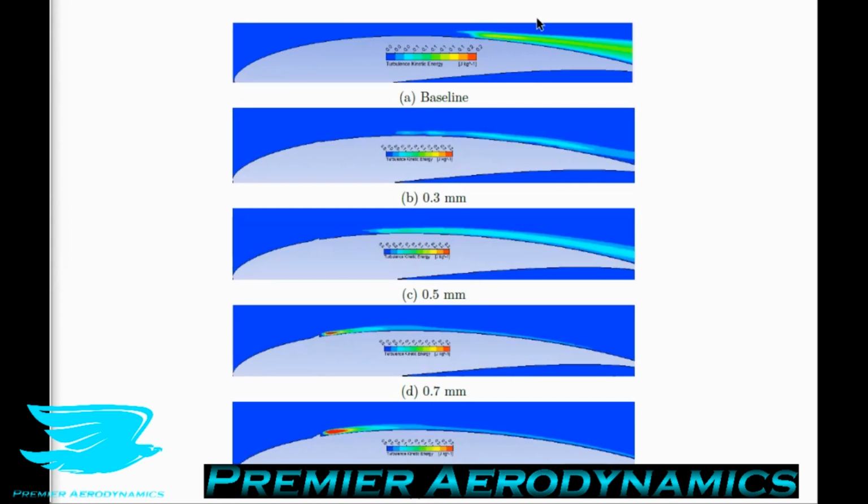So in other words, on the baseline airfoil, we have the flow separating and it's laminar, so we don't really have any turbulent kinetic energy. Turbulent kinetic energy is exactly that: the kinetic energy of the turbulent part of the flow. And we can only really get that if the flow is turbulent. We only get turbulence when the flow starts to reattach, so aft of the LSB. And when the LSB reattaches, there is quite a lot of turbulent kinetic energy happening. So the flow is turbulent afterwards.